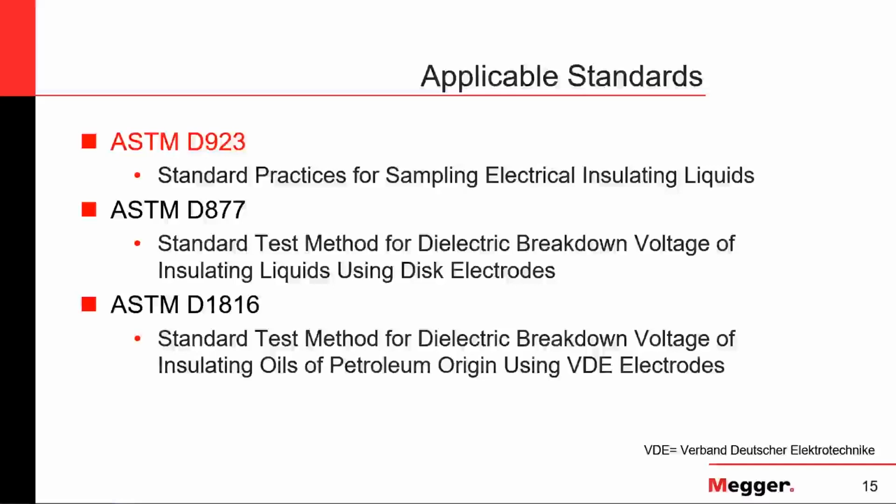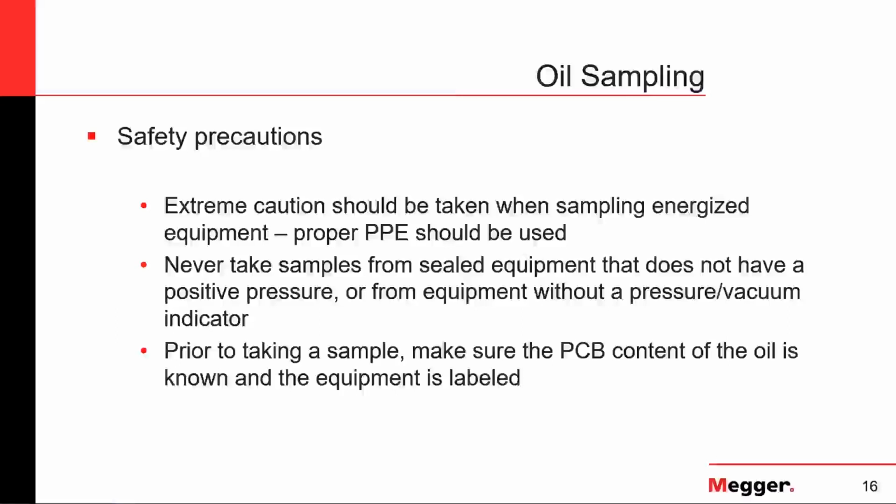For the actual measurements of dielectric breakdown voltage, we're going to look into ASTM D877 and ASTM D1816. Both of those will give us step-by-step procedures to actually make the measurements, and like I mentioned before, they will give us guidelines and recommendations to achieve accurate and valid readings.